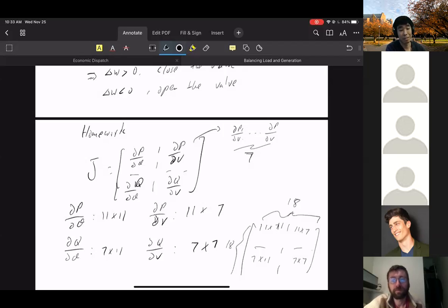If you have time, switch over to not subtract the load, because that will make your life down the line very difficult. You basically have a slack bus that's outputting, I don't know, like 200 megawatts or something in that homework. If you hard coded that in and it's hard to change, that's fine. But later we'll switch over to not do that.